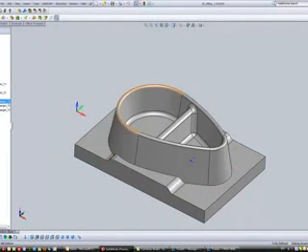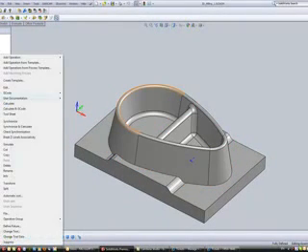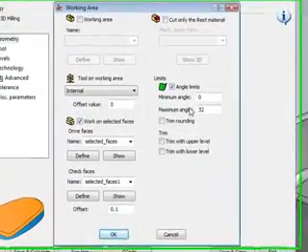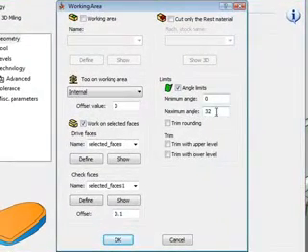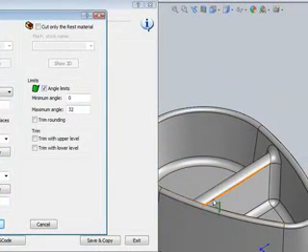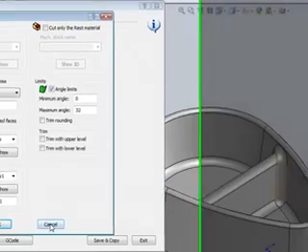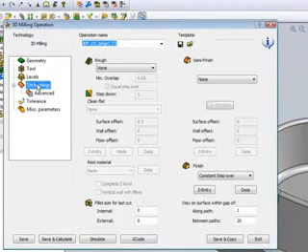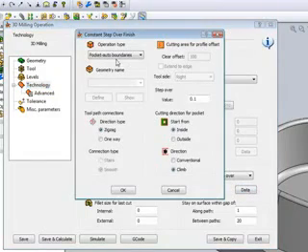Now, in our next operation, we'll be using the same working area, but this time we'll be limiting it between 0 and 32 degrees. In other words, now I do want it to work on these floors and on these radiuses, and the option that I will be using in my technology will be constant step over using pocket auto boundaries.